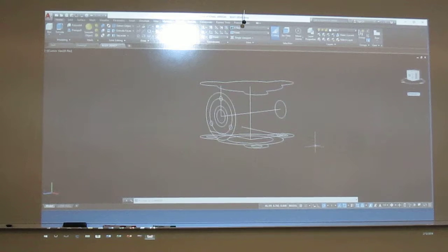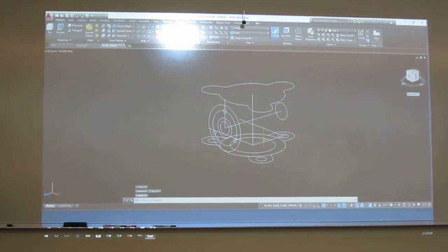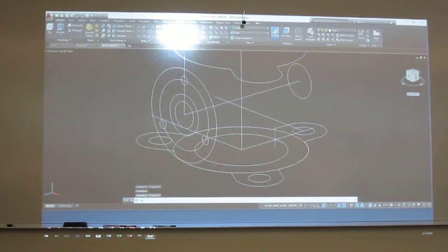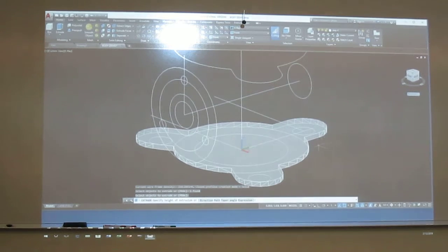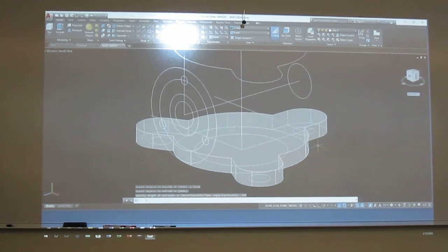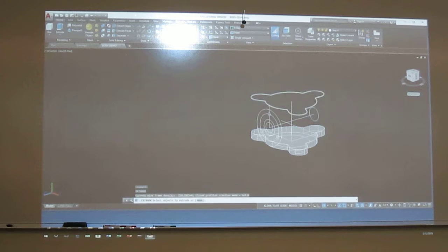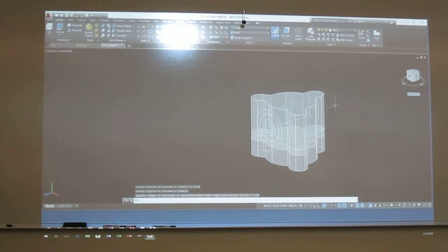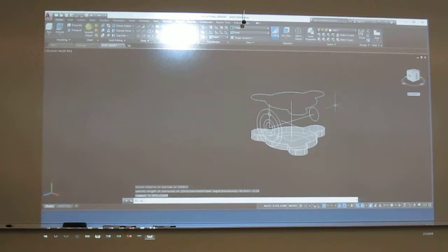Okay. Now, when you're doing these, since you've got the shapes, you don't need to switch UCSs at all. All you need is P-lines. Okay. So I'm going to do this guy with pretty much only the extrude. I'm going to do an extrude, and I'm going to grab this guy, and I'm going up a positive 0.313. Then I'm going to get this one and go to a negative 0.313. Oh, bad typo. Never got the negative sign. Extrude. And this is minus 0.313.